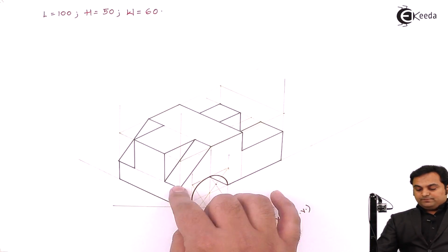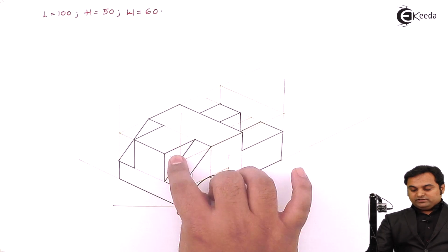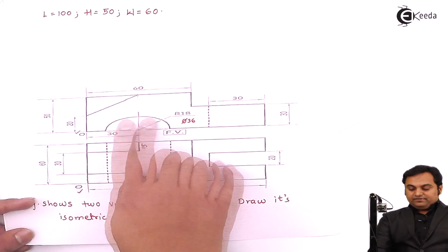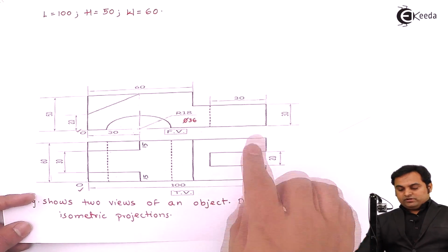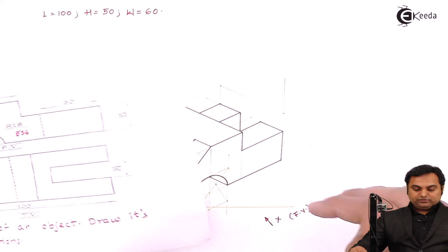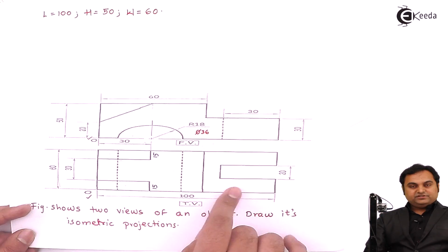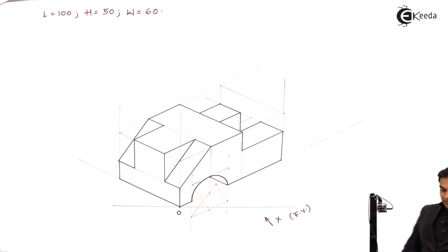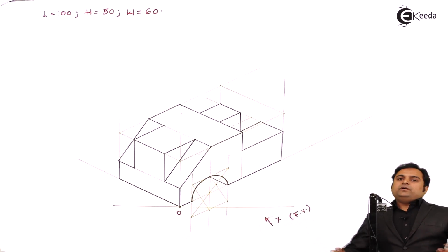Next, the inclined portion, along with this, here this triangle is visible, which is here, and then semicircular groove is throughout. From the front this groove is not seen, so it is hidden, and when I am looking from the top, the complete surface is in this order. There is dark line in between them which indicates change of plane, and here with this we complete the problem.